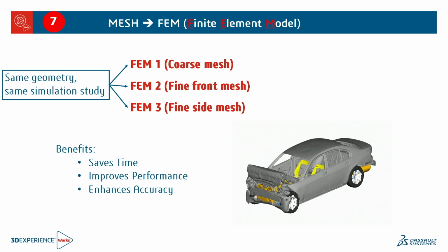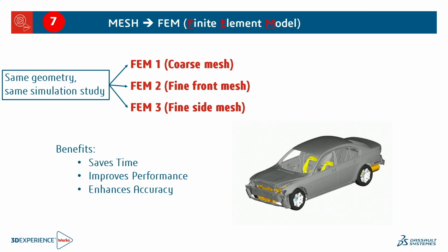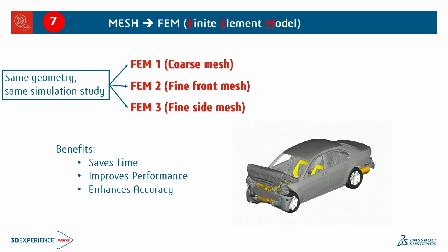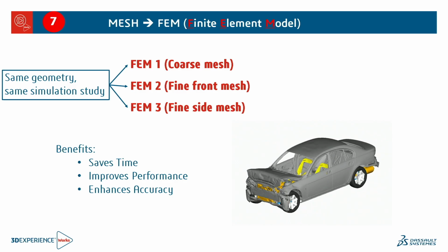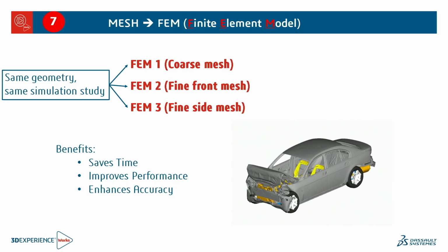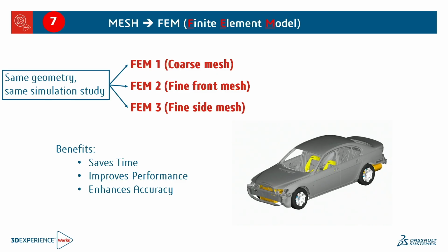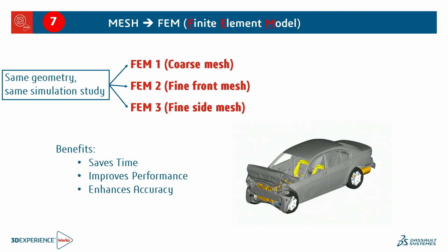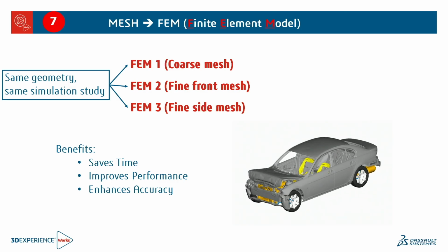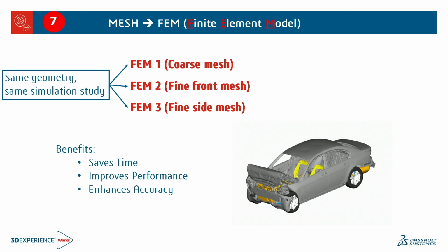To mesh large assemblies? So, Mark, do you want to take that on? Yeah, so I assume you mean go through, run a mesh on many parts inside an assembly. We're not showing it here, but there's a batch meshing routine where you can set up procedures and say, for these types of parts, we want to do this type of mesh. For these types of parts, we want to do this type of mesh. And then you just sequence that all through and it will create a mesh with all of those individually done.